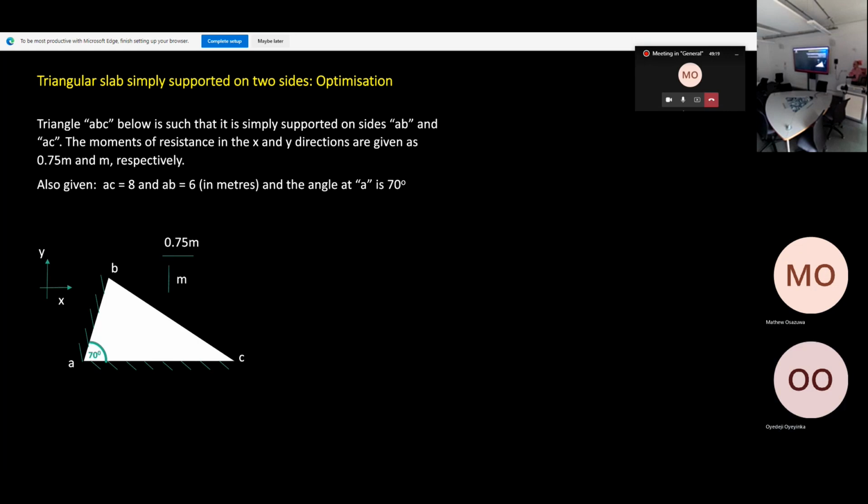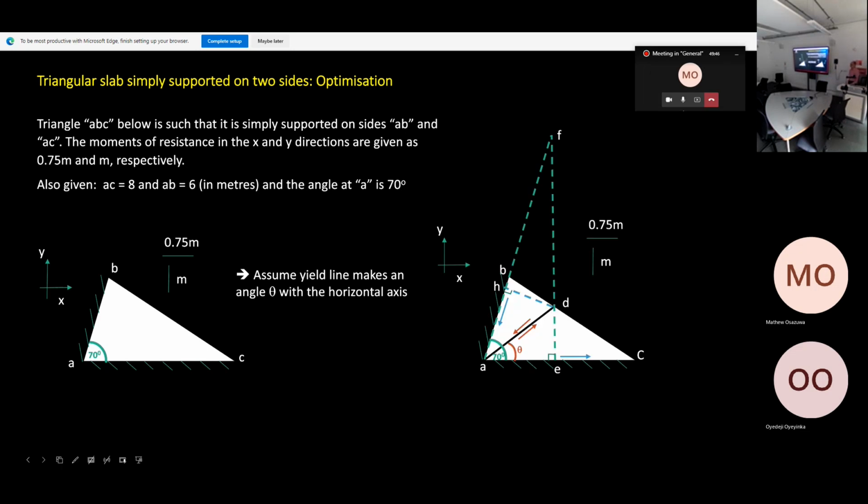Along the edges, a yield line, one single yield line here, somewhere there. Yeah, kind of. So you can have one line here, isn't it? Definitely. Because if it's supported on two edges like this and you load it, there will be a crack forming somewhere that will split it into two, and then it will fail. Clear? Okay.